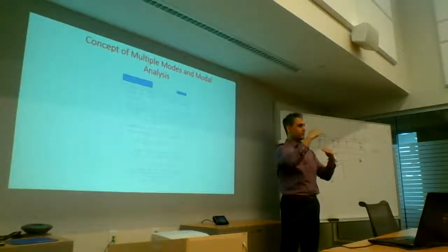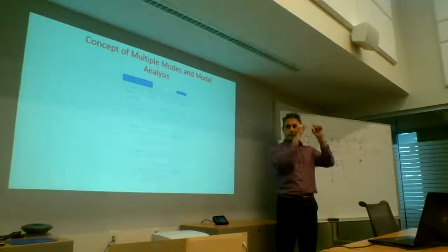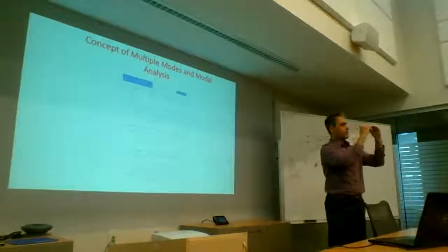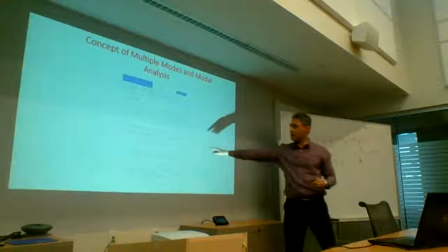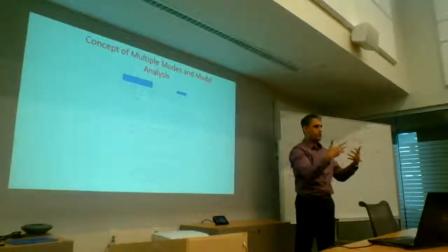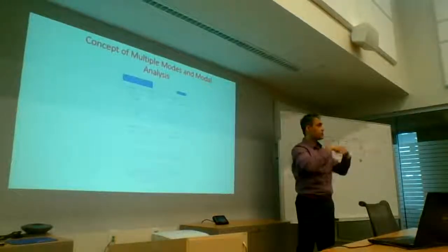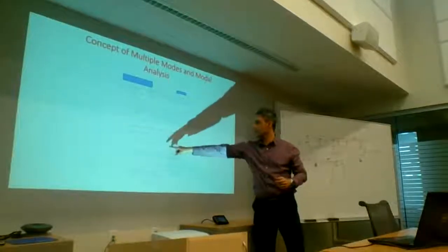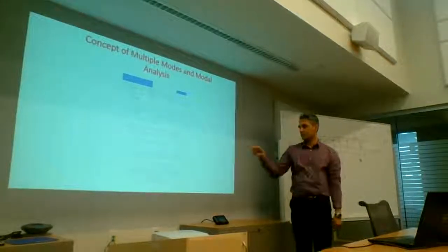You're solving single degree of freedom equations that are decoupled, and at each time instant, you're calculating the actual response for that mode, for that degree of freedom. Now you can add them together for the same time point. But when you go to the response spectrum, you can't do that because those are maximum quantities. Now you can add them all together over all the modes, you sum them, and you get the displacement.